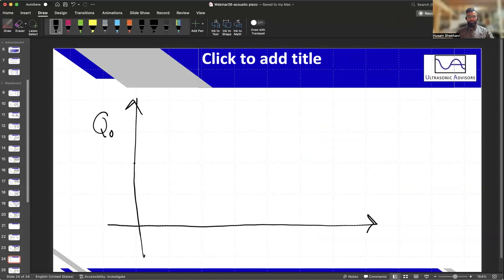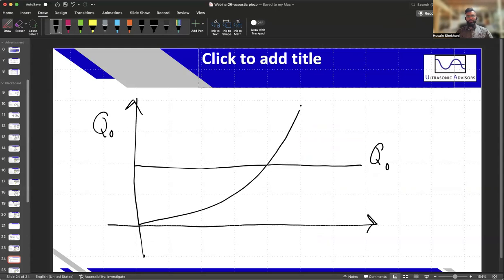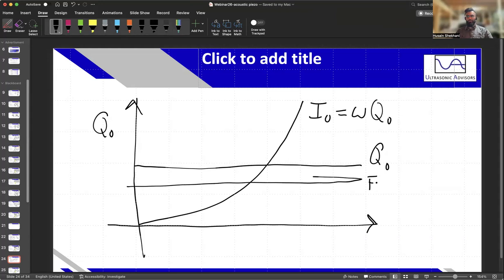And I don't want to make this too long, but for the crystal alone, the amplitude of charge is always going to be the same, and the amplitude of current generated is going to increase with frequency because, well, you can think about it multiple ways. This is the same. I'm just going to draw this too, and this is just force. Force is constant over frequency.